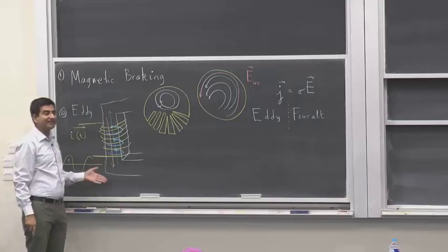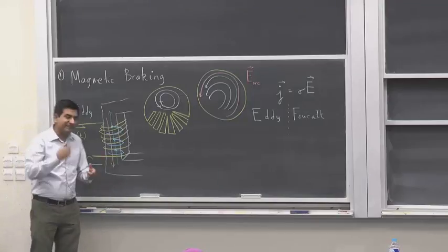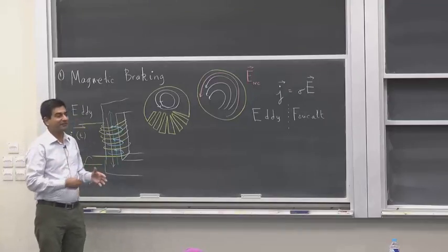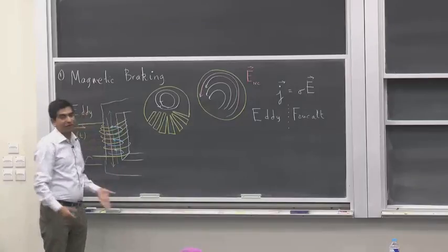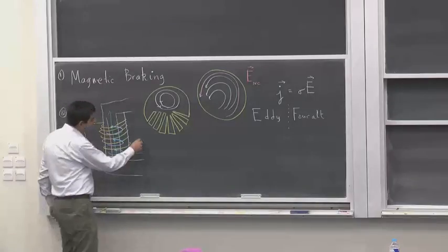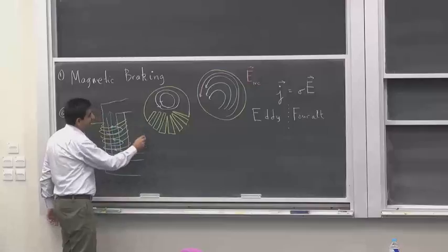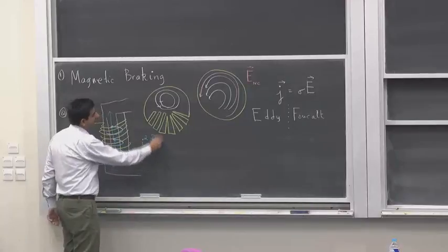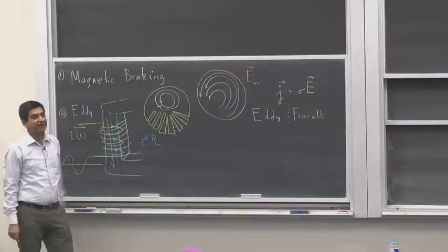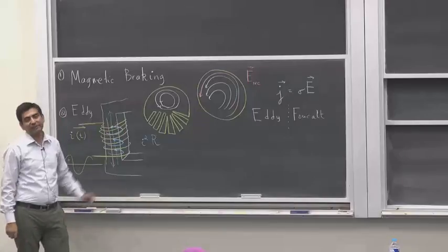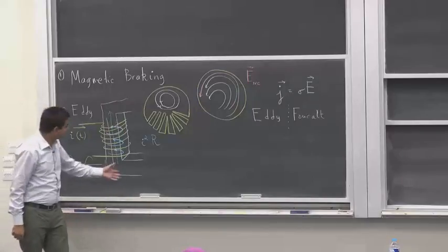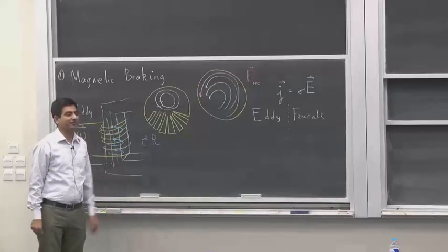Now you want to arrest these currents because these currents will actually cause resistive heating. This material no doubt has resistance. So whenever a current I flows through a resistive material, it produces a heating effect. The amount of energy that it produces per unit time is I squared R. And this transformer core heats up.